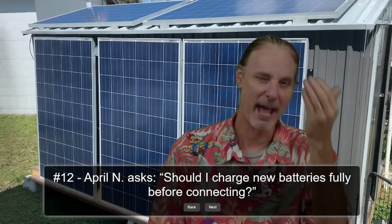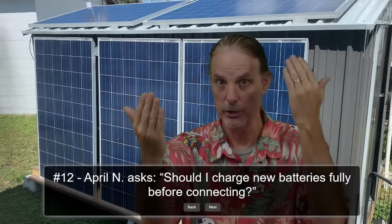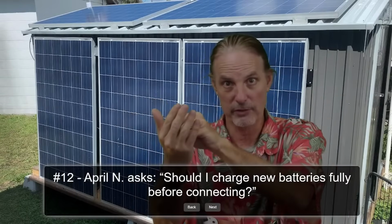Otherwise, if you turn on a battery that has 56 volts on it and the other battery has 52 volts, you're going to see a lot of energy come out of this 56 volt and try to charge that 52 volt.